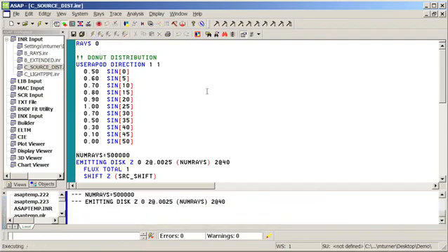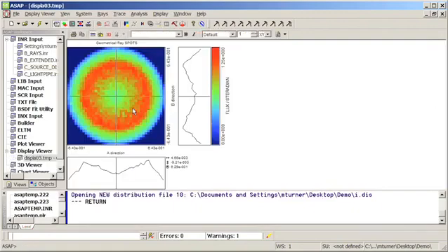So I'm going to simply show you what the rays look like coming from our source in a direction cosine space. And as you can see from our apodization profile here, most of the energy is directed towards an angle of 25 degrees, and then it tapers off from there, and there's no energy beyond 50 degrees, giving us basically a donut-shaped distribution. If you wonder why we might use something like this, it is very representative of the output from something like a VCSEL.